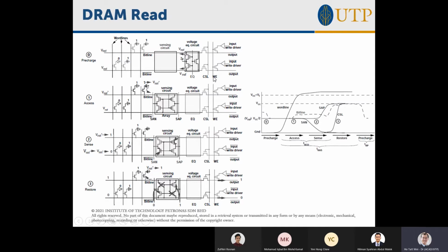And that's why this is called write enable, you see. If the write enable pin is turned on, you are letting the data input actually drive this bit line. If write enable is 0, you are just reading whatever value of the bit, and sending it to the output line. And this is actually the chip select. The chip select is just basically connecting or disconnecting the DRAM to the output line. That's all.